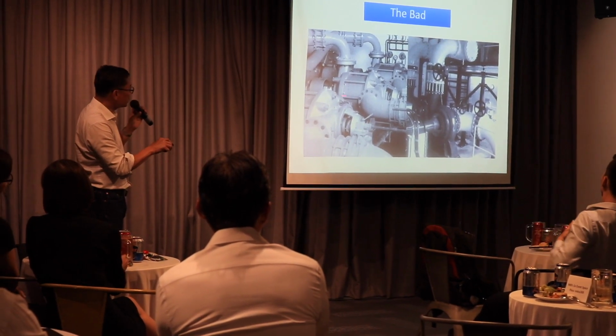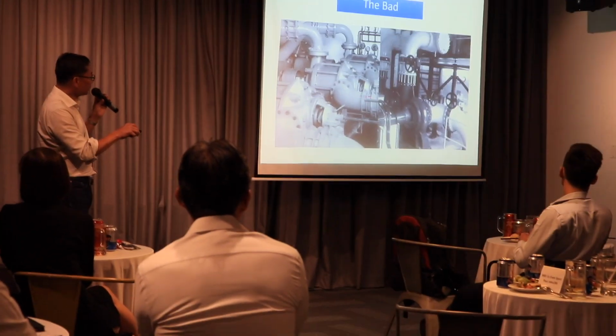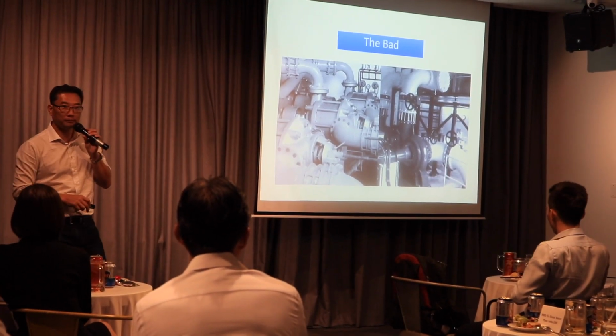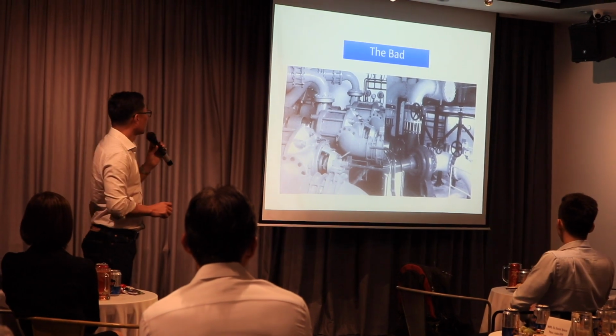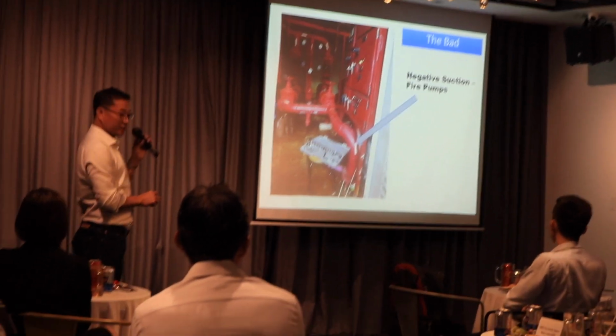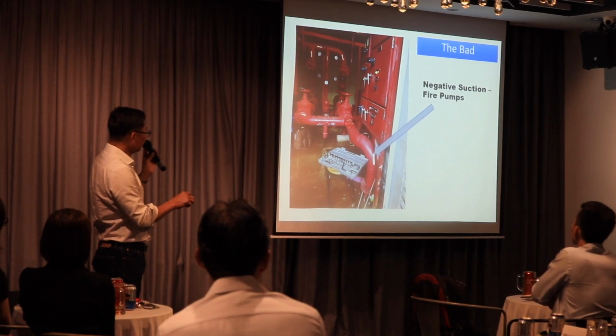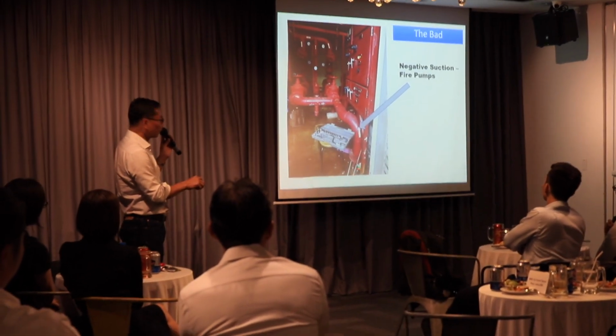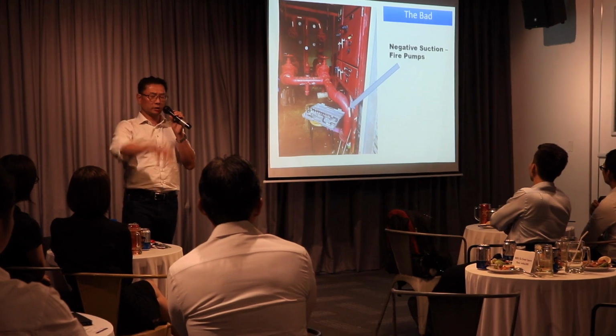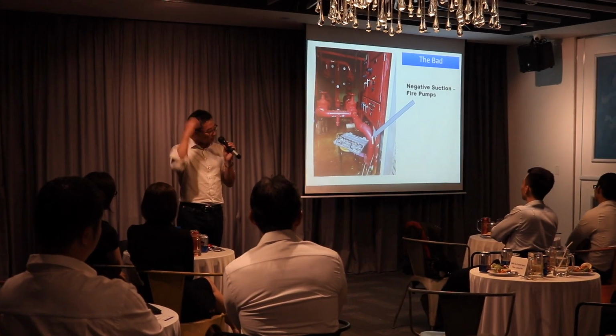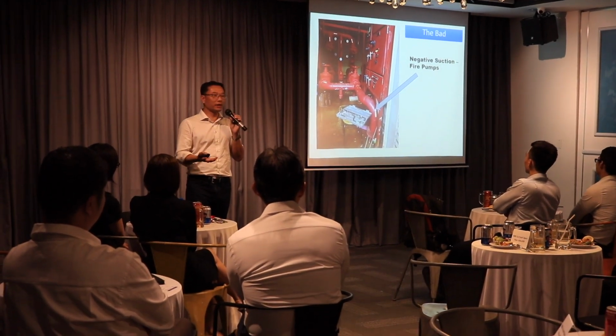Right. Look at this multi-stage pump. This is even worse. Straight away the inlet comes and you go into the pump. This is in Singapore, unfortunately. You see the pump behind, the tank below. This pipe is very long. The contractor said, oh, the tank is just below. So after repairing, it still cannot work.